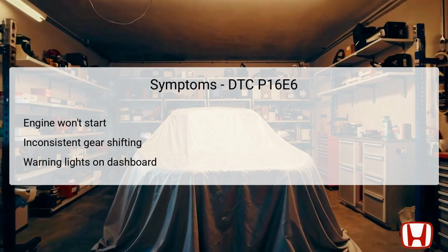broader electrical issue. Additionally, inconsistent gear shifting may occur where the vehicle may unexpectedly shift gears or fail to recognize the current gear, impacting driving stability. Finally, dashboard warning lights may illuminate, alerting the driver to a fault within the starting or transmission systems. Recognizing these symptoms is crucial for initiating timely diagnostics.